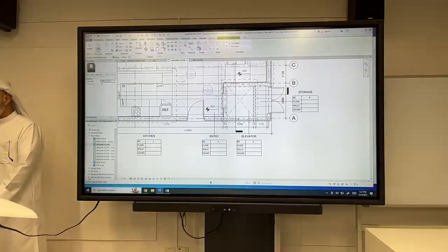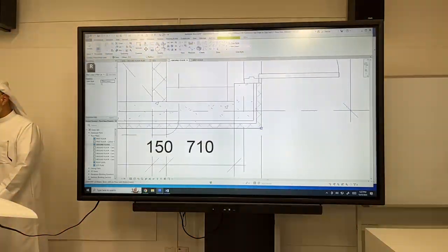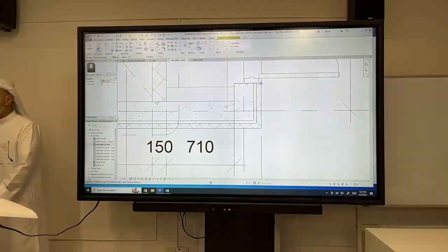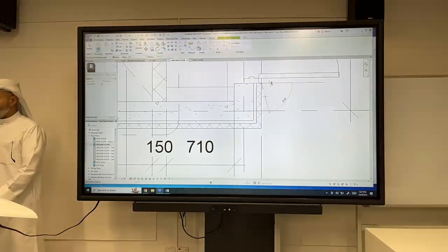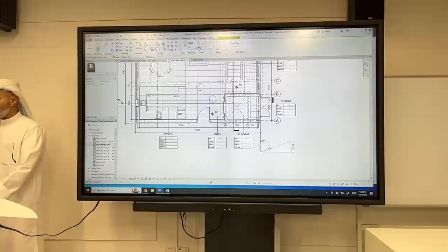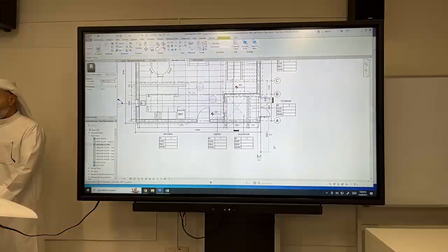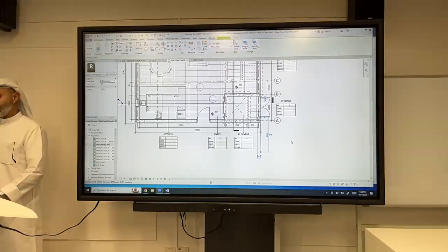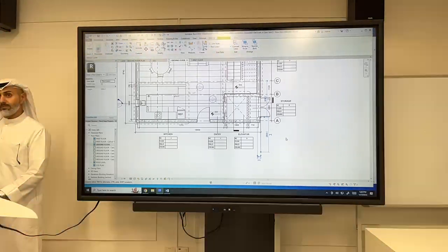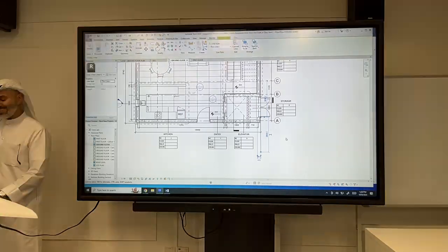DL, detail line. I come and I want to do it over the wall. Don't enter the edge, because I want it to span the wall. I'm going to draw a long line downward. It doesn't matter what the height of this line is. I select it and then I copy it. What's the copy shortcut? CO.